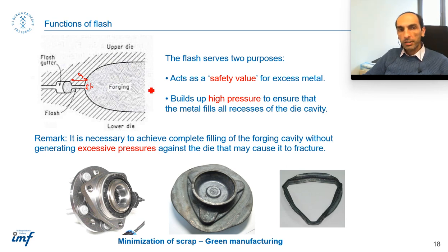Here this ratio is not too big, but here, because H is so small, the A to H ratio is big. So the flash is designed in this way intentionally, so it can apply some reverse force, and then the material will fill the die instead of escaping.